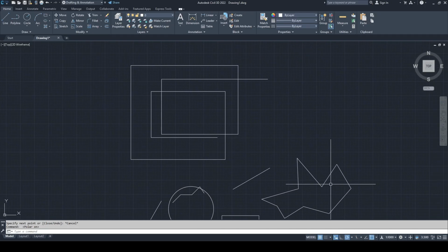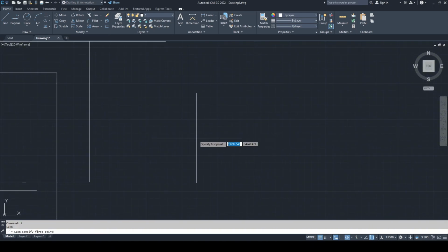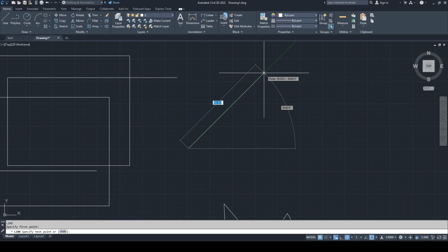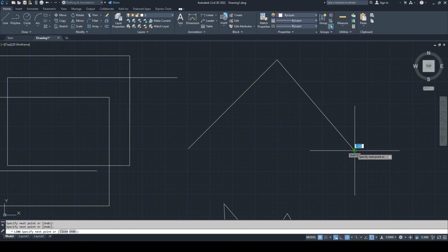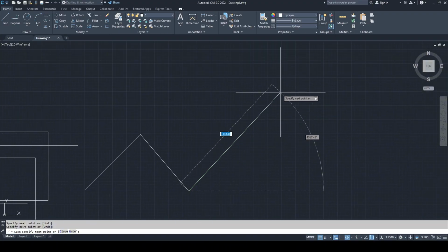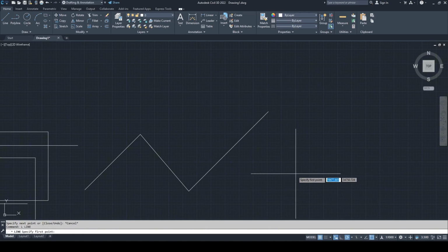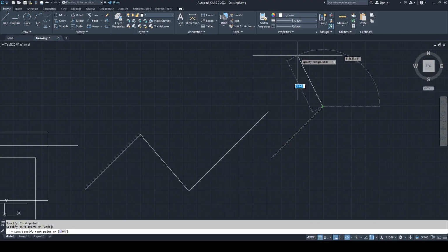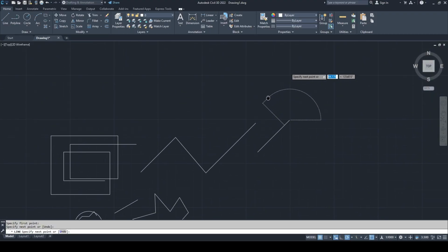Now this is polar tracking, as I showed you before. It will draw your line on an angle. Now you see, I can extend the line and it is not stopping on 10 because it was this option, the snap mode. In this option, polar tracking, I can extend the line wherever I want to, or I can also put the value, for example 100. I will press tab and I will press the angle of 45. So it will read my dimensions and apply on the drawing.